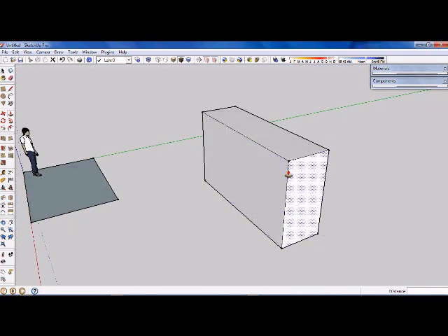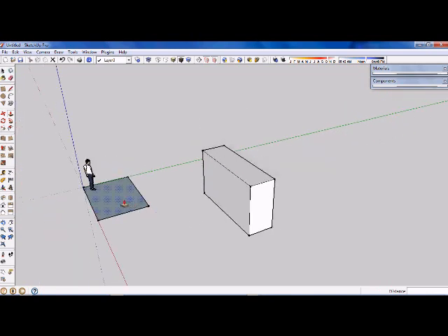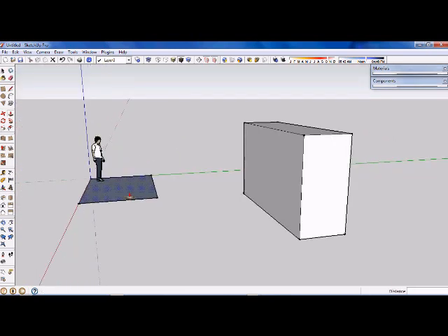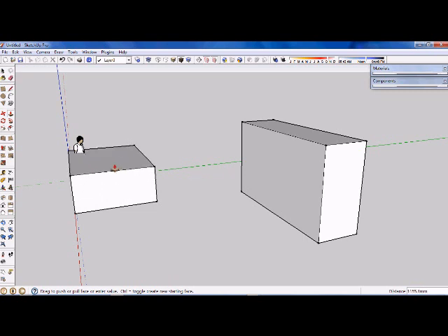I'll do that again to this one over through here, but this time I'll just roughly use the second option, roughly drag and drop where you think it is just by eye, and then after you've dropped it, before going on and doing anything else, type an actual number like 1200 and press enter. It then snapped that height to be exactly 1200 high.